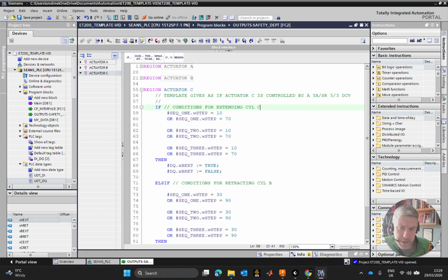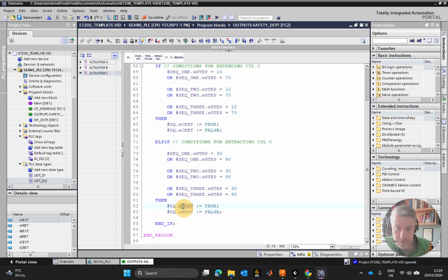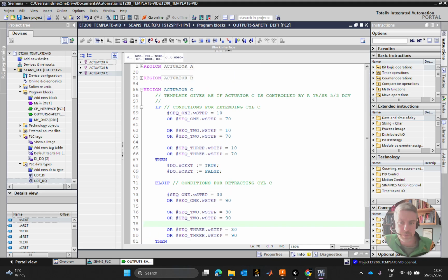Right. I did always write these up here with ranges. Anytime that I had a spring, I did use a range in it. It's going to change all my B's to C's, but just what I'm thinking now, it's a while since I wrote these up from the start. My own templates use a range, but I can't see the reason why I would have a range in it, other than the fact that it is a spring. But given that the spring snaps back to a neutral position, it shouldn't act untoward. It shouldn't retract cylinders that otherwise should be extended, and vice versa.